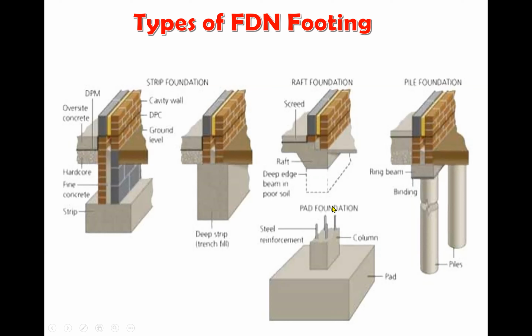Of course, if you're doing a commercial building, it is recommended that you do soil tests. So you get a soils engineer to come in, take a sample of the soil, go to the lab and test it. They do the calculation, and they will determine, based on the bearing capacity of the soil and the amount of load that is going to be exerted on that strata, the earth, the type of foundation. So these are recommendations based on typical building size, or you can recommend what type of foundation is suitable.